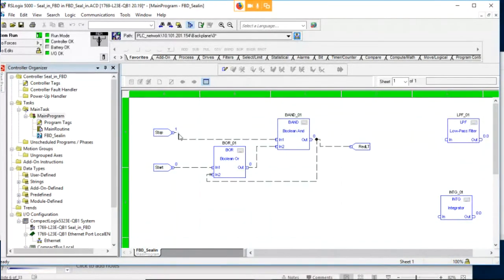And the stop button, of course, is the physical button on the PLC, and it's wired closed. So even though nobody's pressing it, it's wired closed, so it's feeding a 1 as our input. So we've got a 1 coming in through the stop, but our start is a 0 and our red light is a 0. So 1 and a 0 is a 0. So this just maintains this 0 here.